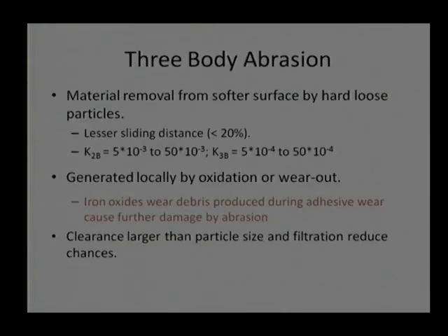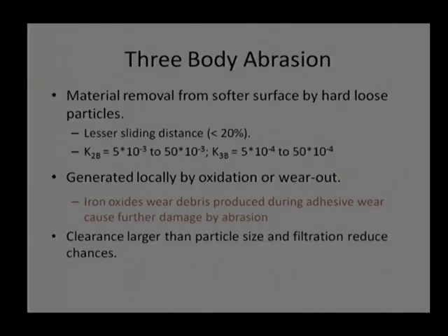That was 2 body abrasion. Now, we can think about 3 body abrasion also. As I mentioned initially, 2 body abrasion is more harmful compared to 3 body abrasion, and this slide is giving the reason. When a particle is detached from the surface, it does not have any rigidity. If you allow movement of the particle, there is a possibility of sliding as well as rolling, and because rolling has a lesser coefficient of friction, rolling will be more dominant. For the same force, rolling will be more dominant compared to sliding, if the shape is proper.